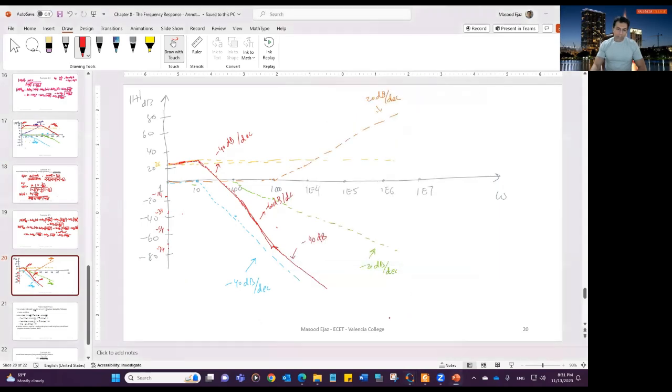All right, so Bode plot is continued. I did discuss with you if you have a square power or cube power. If it's zeros, then it's going to increase by 40 decibel per decade or 60 decibel per decade based upon what is the power.